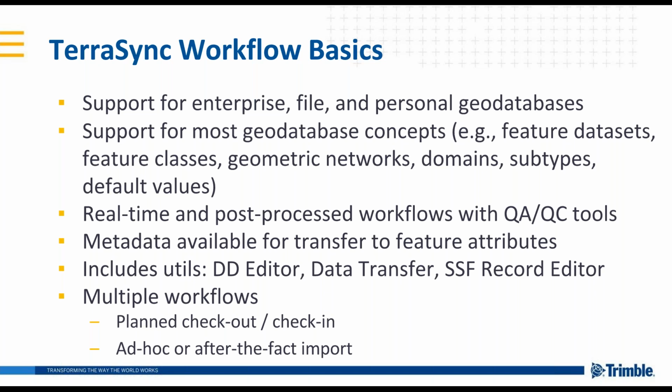So although the post-processing is done in ArcMap from within the Positions desktop environment, you also have the full ability to use all the capabilities of TerraSync with setting up TerraSync for real-time sources, etc. And any data that comes back in will be seen as being real-time and corrected in the field.